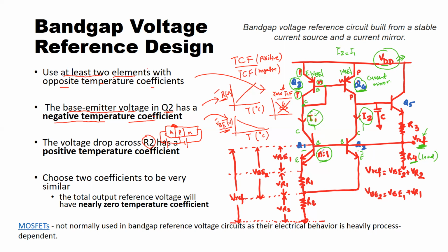So this is like a fabrication factor. You basically manufacture a transistor Q1 to be larger in area than Q2 so that it has a larger current capacity. That's why there are two emitters showing for this transistor. Okay, and now look at this.